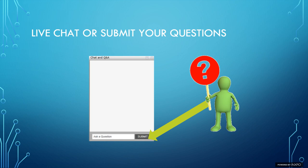The particle count, that's a little bit of a two-sided sword. Typically, most of the applications are not that critical, but for those that are, there are some, let me just say, $40,000, $50,000 sensors that can do this as an online one. There's also a requirement or recommendation that food processing plants have at least a yearly or sometimes biannual inspection of the air quality. It all depends on how critical it is and what the damage is in terms of monetary and to your customers. That's what determines what compressor type, what cleaner treatment, and what kind of monitoring I have to employ to be able to sleep at night.